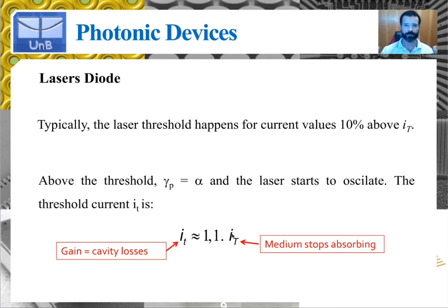So all of the scattering losses due to Rayleigh scattering, scattering in the sidewalls of the optical waveguide, which is formed in the active region by the means that we discussed previously. And the losses at the reflectors of the laser itself, right? So if it's a Fabry-Perot laser, it will have cleaved facets on the chip, off of which the beam of light will bounce.